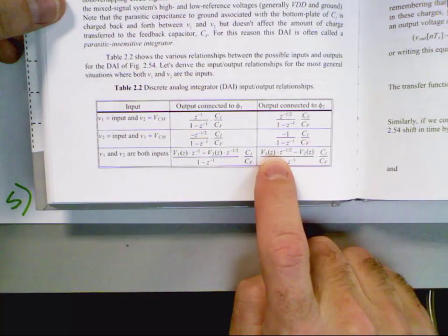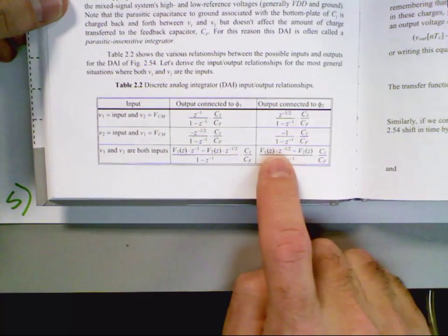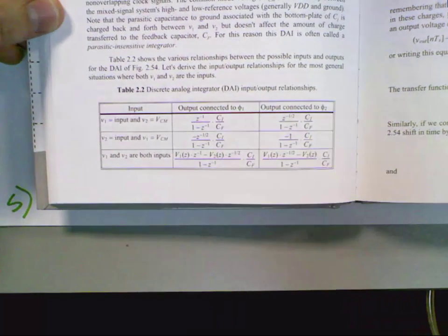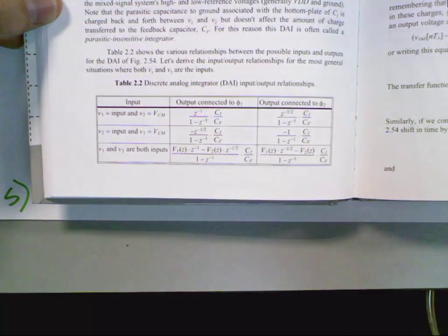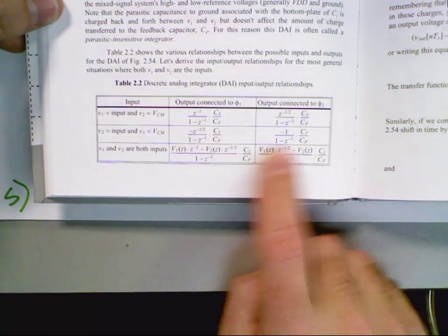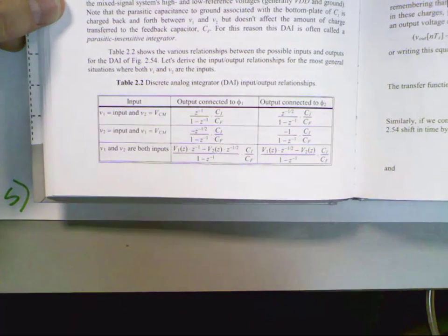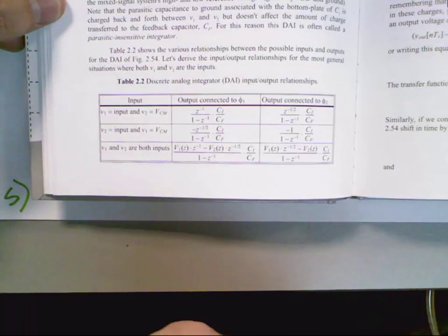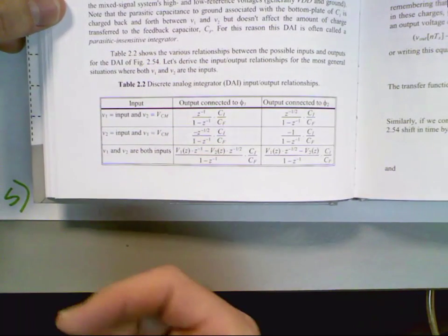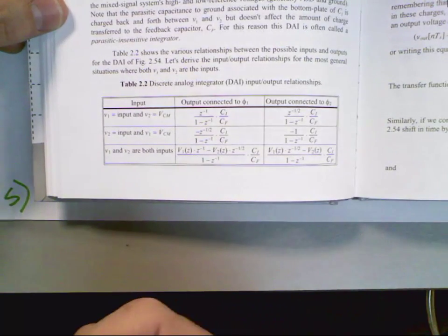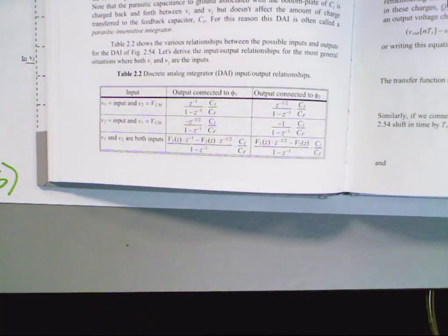Would everybody agree that this little delay of the input is just a half clock cycle, really? When I implement the second order modulator, instead of the input coming in at 0, the input comes in a little bit later. But it doesn't influence the implementation. It just means my input comes a little bit later. So the true transfer function for the second order would be Z to the minus 3/2 instead of Z to the minus 1. It just means my input's coming a little bit later. Doesn't influence anything else in the circuit. Did I lose anybody on that?